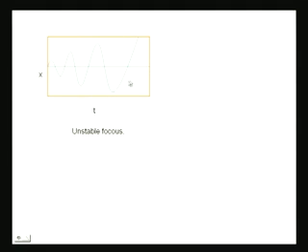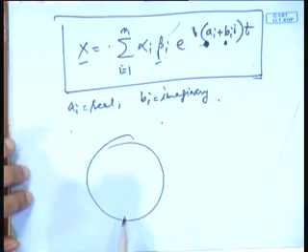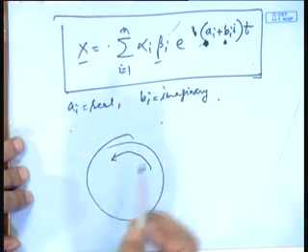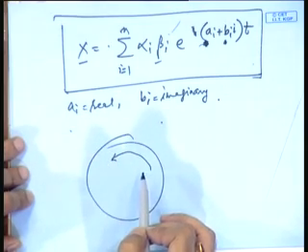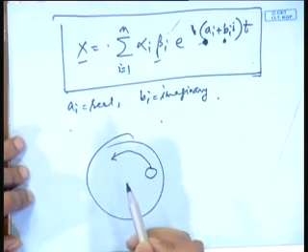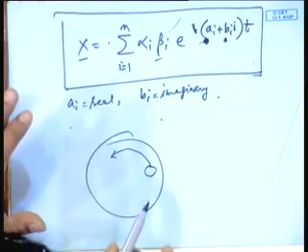The reason is that typically there is an oscillatory part, and this happens especially in what kind of coordinates do you think? What kind of systems? In circular or spherical systems, in cylindrical or spherical systems. Why? Because you have the radial direction, let us say in the cylindrical system, and these oscillations happen in theta. So, the hotspot starts to rotate. These oscillations will actually lead to rotation of the hotspot. So, you have a hotspot over here, and in practical systems, this is what happens.